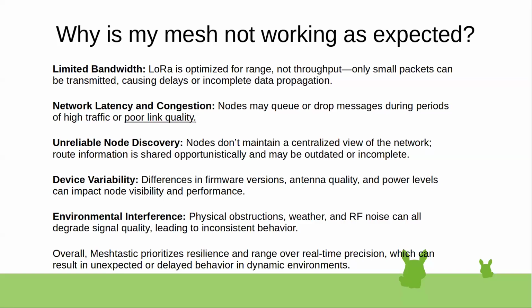So the first thing: limited bandwidth. LoRa is optimized for range, not throughput. So only small packets can be transmitted, causing delays and incomplete data propagation. This next piece, I think, is the key as to why people say this doesn't work: network latency and congestion.